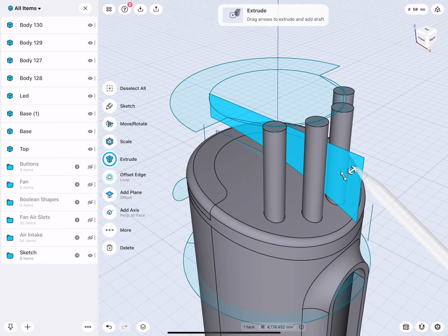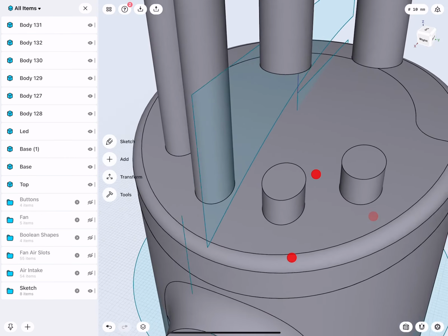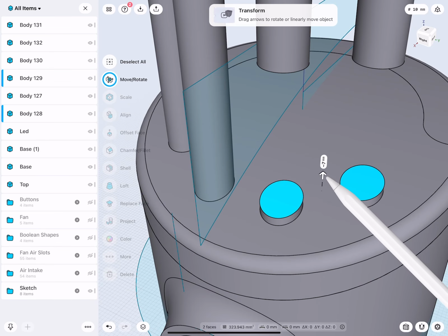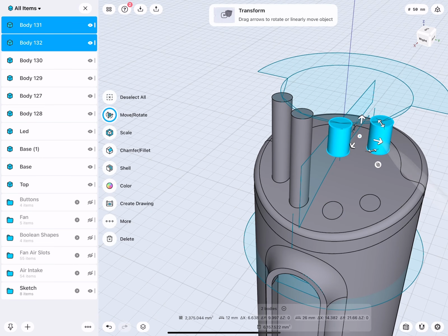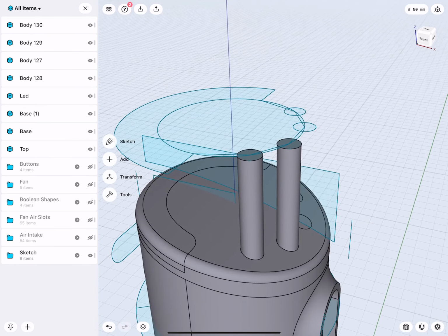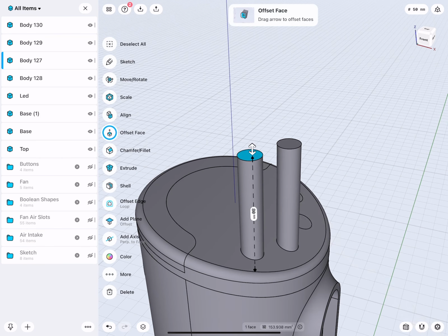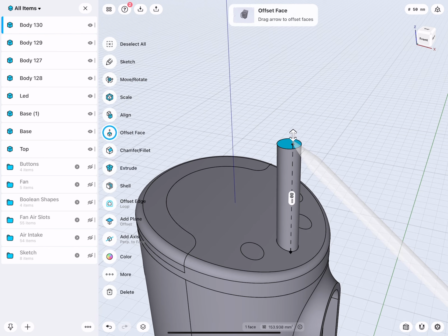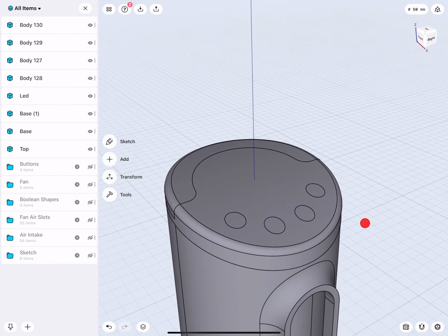I could go this way: I cut, and then move these faces 10 millimeters down. Well, that works. And this I can remove. Or what simply will be faster: it's one face, target face, and replace face. That face, this face, and replace. Super easy. Okay.